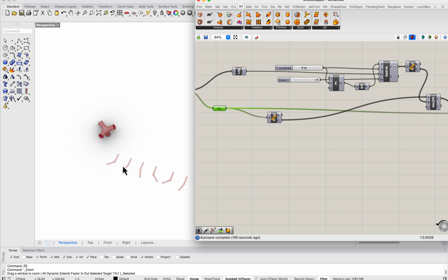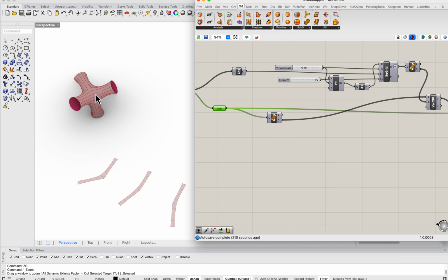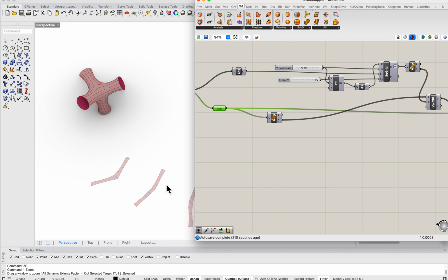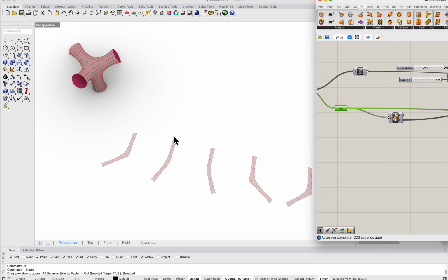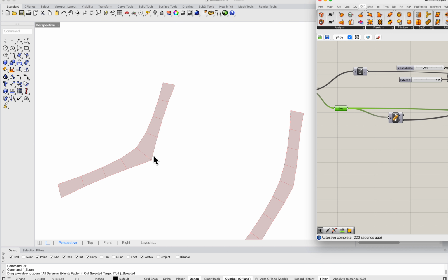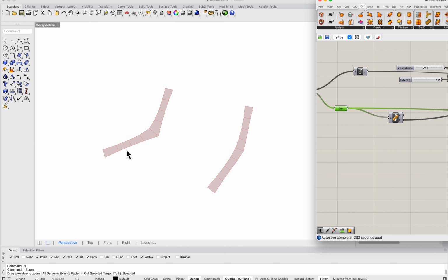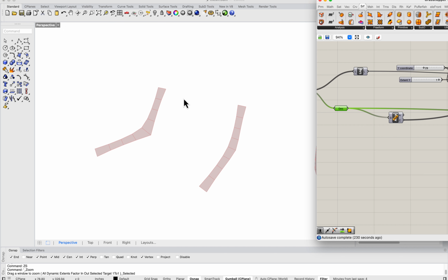Now I'm going to run this on these individual strips, but imagine having a more complex form and more unique pieces, then you might have to split them into different parts. Maybe we can also look into another file that does that. One thing I'm doing here is spreading out the individual parts, but then what I want to do is process these edges so that we can have joinery. For the joints, I'm envisioning this to be manufactured out of, let's say, thick cardboard, and then we can maybe use zip ties to tie individual edges.